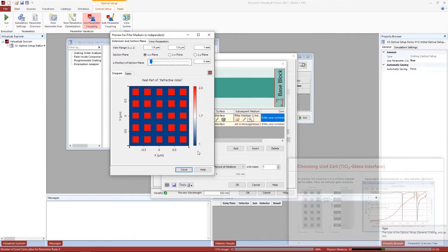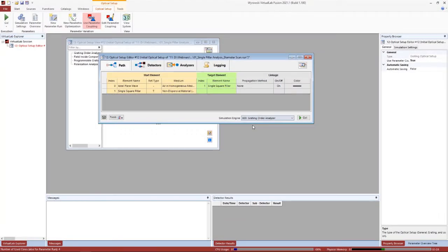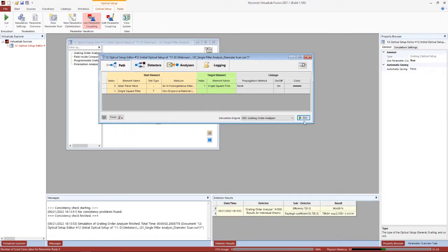Then we're going to perform a simulation of this structure with a plane wave as our input field, and we're going to read the phase of the field after it is propagated through a pillar grating defined in this way. And then we're going to repeat the same process again for a pillar grating where all the pillars are exactly the same to each other, but where these pillars have a different size from those of the previous simulation.